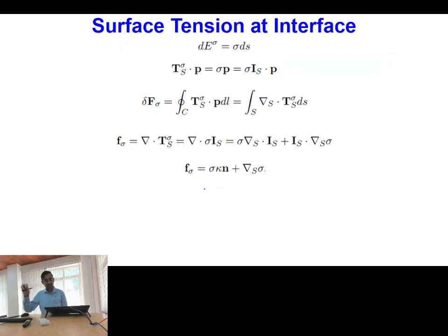Okay, once we have defined these, we also need to specify the balance of the forces, and we know that when we have the presence of an interface, the additional force other than the shear and the normal forces is the surface tension force. Okay, so that also acts in terms of tangential and normal force only, but in addition to the pressure force and the viscous forces. Okay, in addition to pressure and viscous forces, one additional force that can come is our surface tension force.